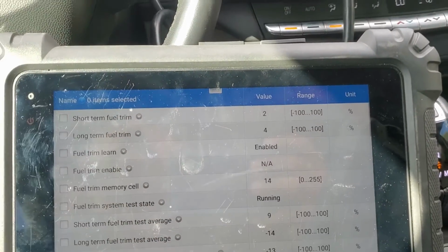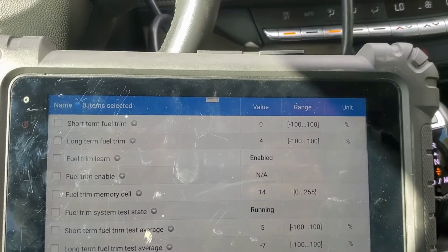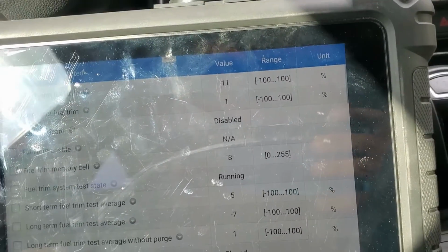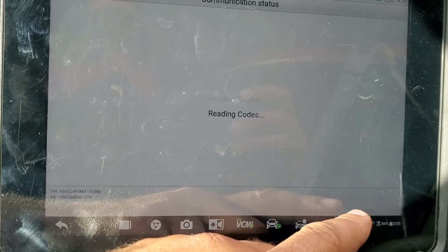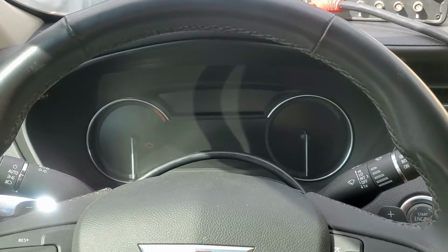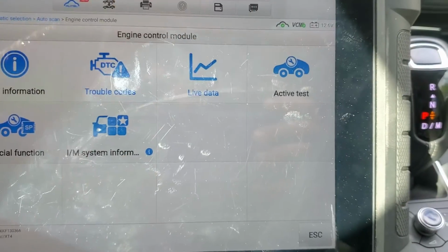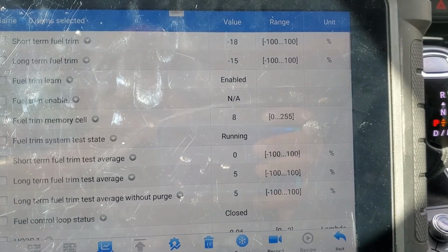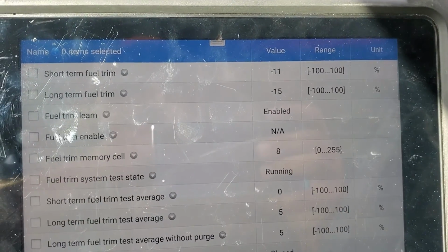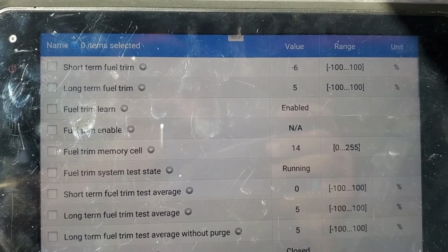Okay, I'm gonna stop here, give the car to the customer one more time. I need him to drive it. Stay tuned for updates. Okay, after some time waiting, I'm reading codes. Nothing popping out. And do we still have good fuel trims? Let's watch them. Yeah, they're good.